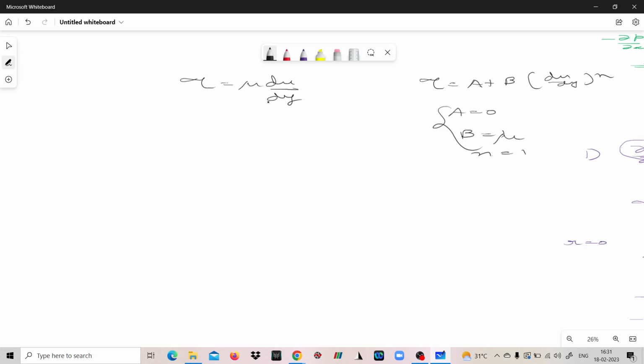Now, what is y basically? Y is the distance measured from the pipe wall. So this is the figure. This is the pipe wall. If this is the pipe center, small r is measured from the center of the pipe. When you write Newton's law of viscosity, this y varies from the solid boundary. So if you consider only one half, either the portion below the center line of the pipe or the portion above it, from the solid portion, this is y.